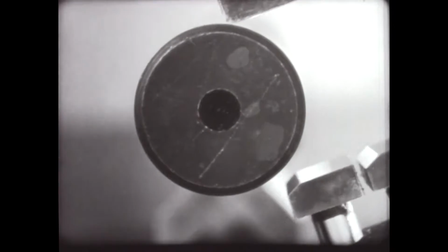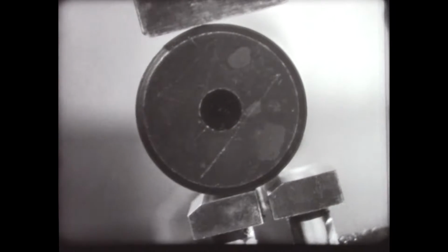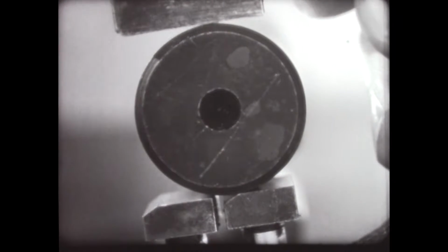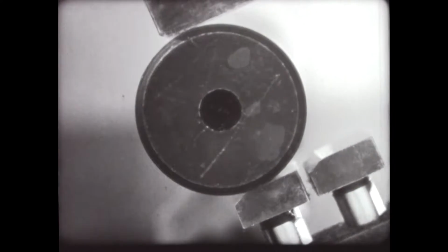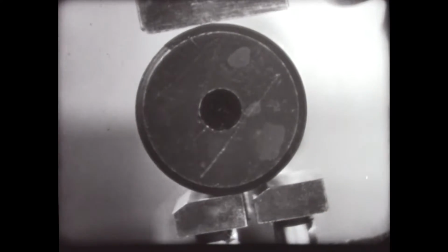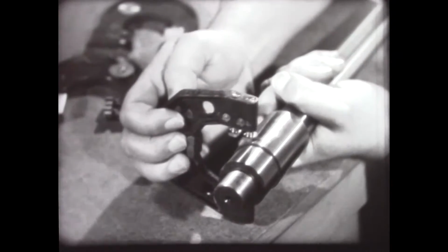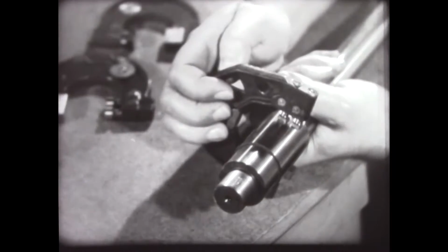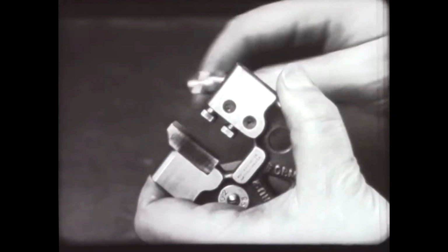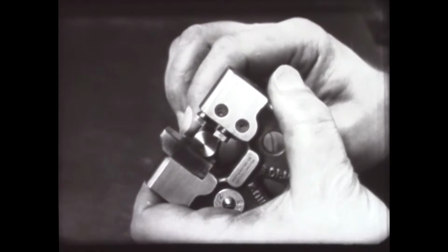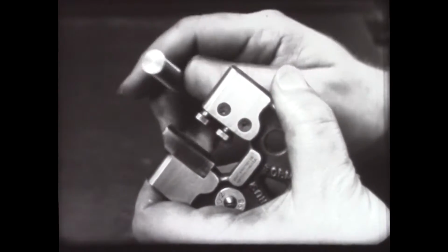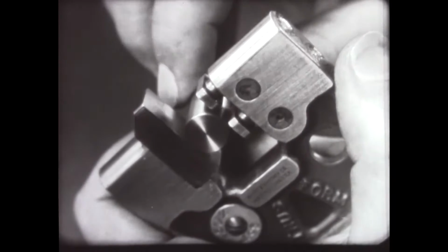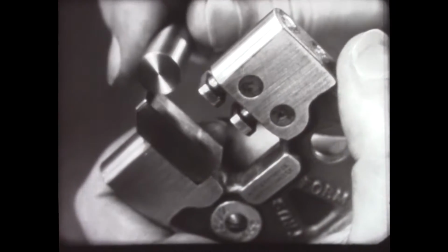If the go button does not pass freely, the gauge should not be forced. Remember that the go button is set out as far as the tolerance will allow. Forcing it past an oversized part may damage the gauge and render it useless for precision measurements. Handling the gauge in the correct manner will assure its precision over a long period of time. To gauge a small part, it is rolled gently into the gauge and under the go button. If it is stopped by the not go button, its dimension is within the tolerance allowed.